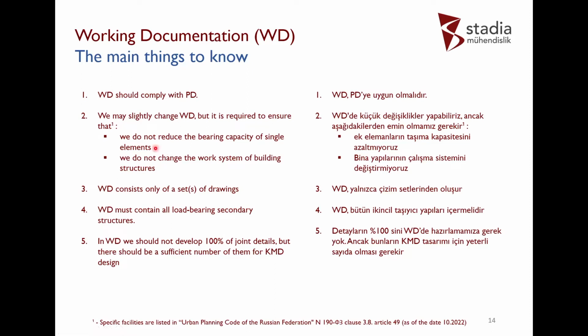Working hours, it takes a few months usually. So I would recommend to take project documentation, and if you are recalculating this documentation, you can just increase sections, not decrease. And also we should not change working system of building structures. For example, if in project documentation we have braces, we should not delete them, as I told before, because it will lead to necessity to go again to expertise. It's not needed by anyone.